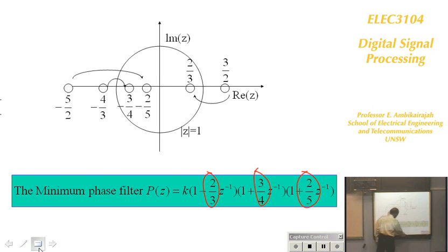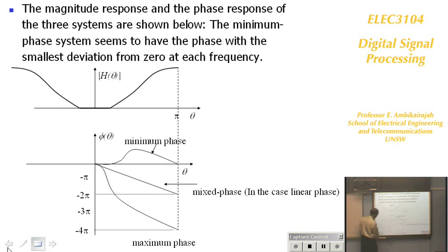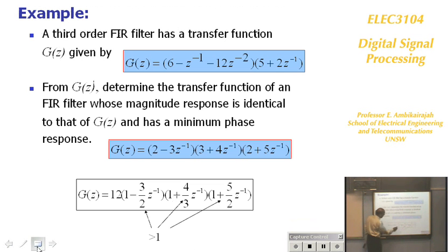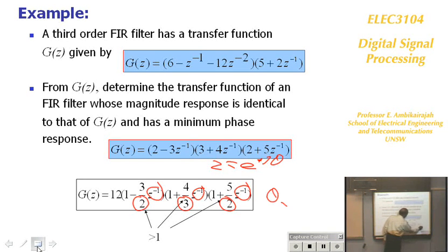Now what happened is, you can have a look here. If you go back here, that multiplied by that, look at the DC gain. Those three, DC gain means that's 1, that's 1, that's 1. Because e to the minus j theta is equal to e to the j theta. Theta equal to 0 means that's equal to 1. Right? That means these are 1. So find the gain on the top and the bottom, DC gain, and you will find you have 12 here. To have the same DC gain,